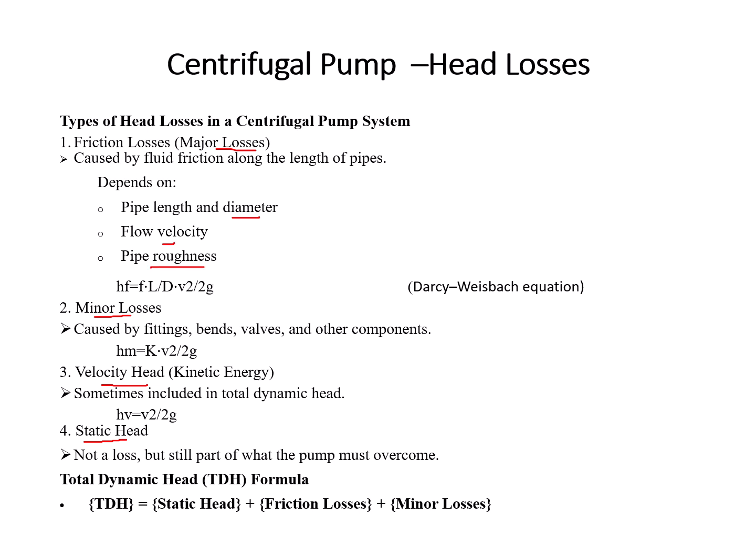Like if you are using PVC, which is a smooth surface, you will reduce the losses compared to using black steel pipes. That's why whenever we can use plastic pipes or PVC pipes, it is better than using rough surface pipes.